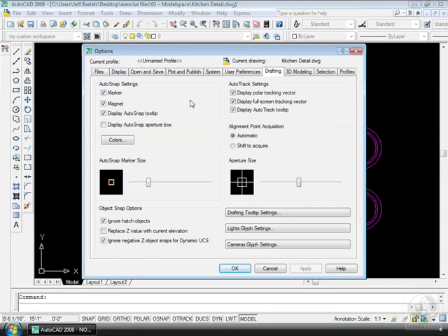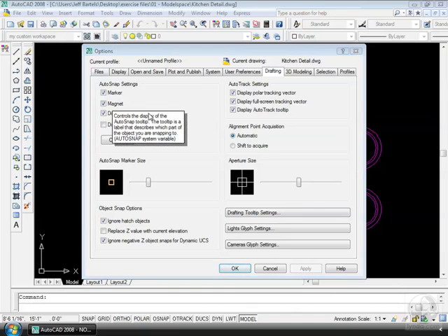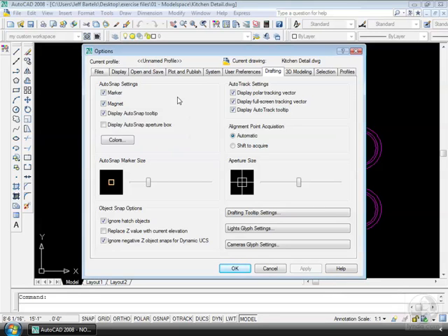What I'm going to do first is show you how you can get information about what each of these options does. If I come up to the upper right-hand corner of the Options dialog, notice I've got a little question mark button. This represents a help feature. If I click on this button, AutoCAD puts the question mark on my cursor, and then I can come over and left-click on the option of my choice, and AutoCAD will tell me what that option does. Let me hit Escape to clear the help information, and let's change some settings.